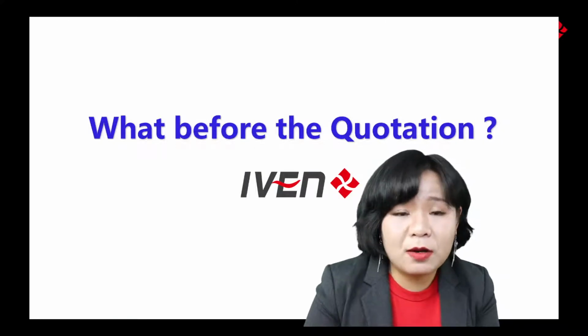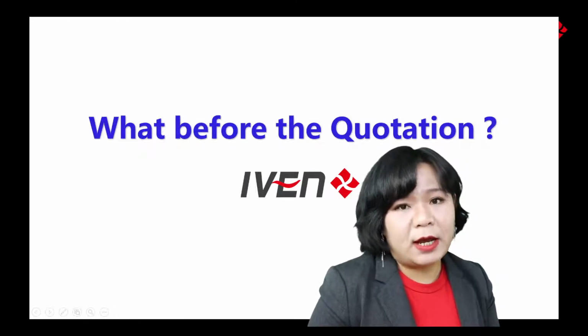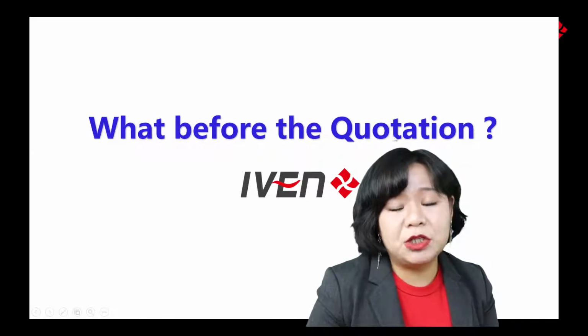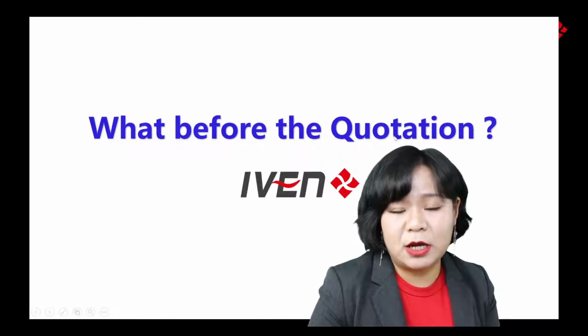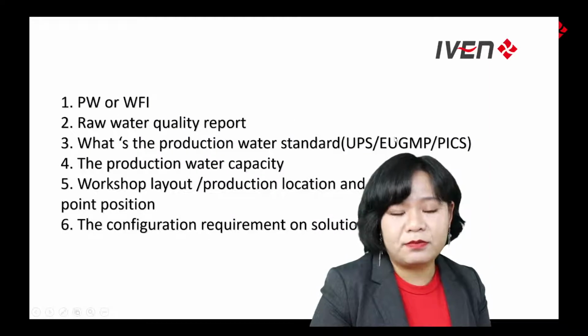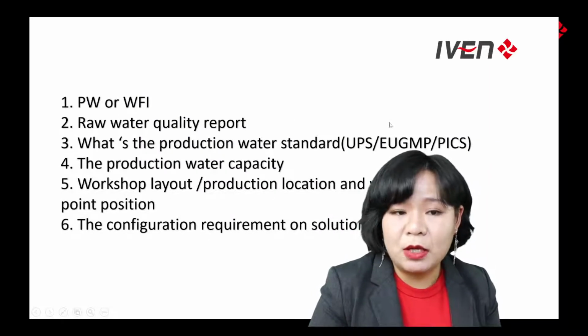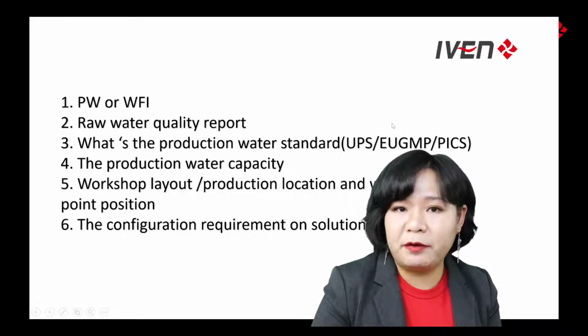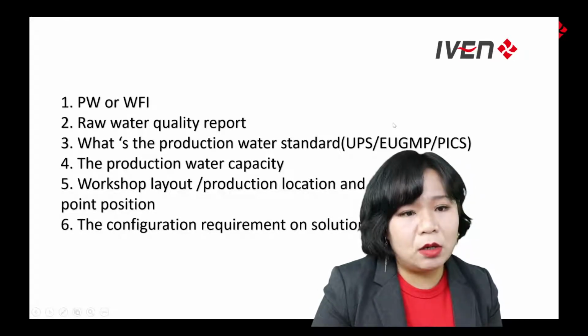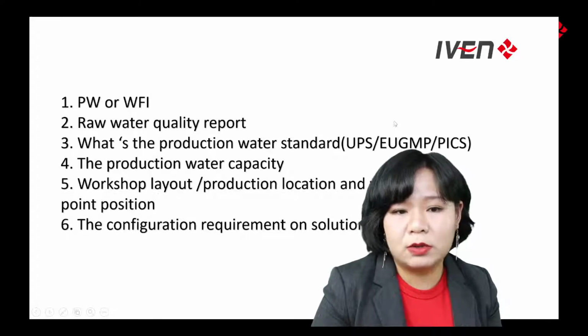Okay, you may wonder what we need before the quotation. What shall we need to figure out for the quotation we can do for you? Before the quotation, we need to know whether you want to make PW or WFI, and what's your raw water quality report?